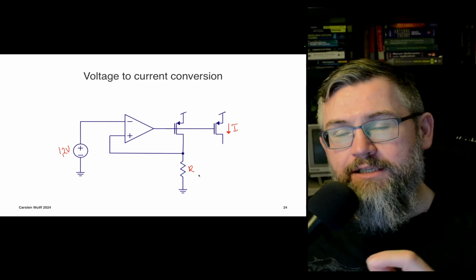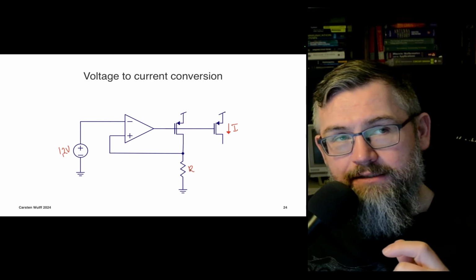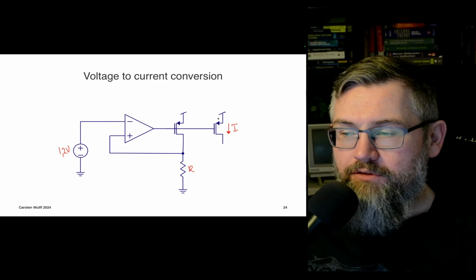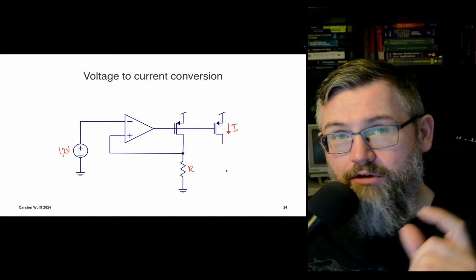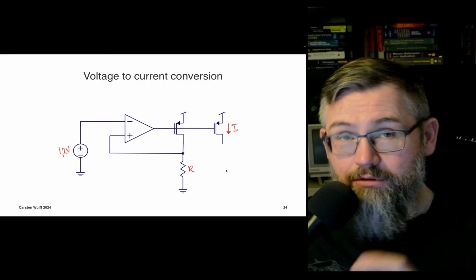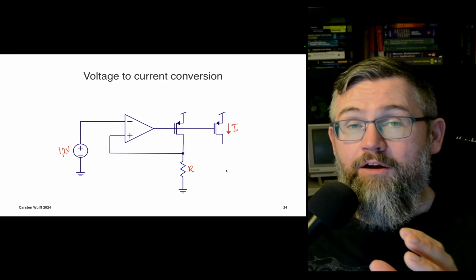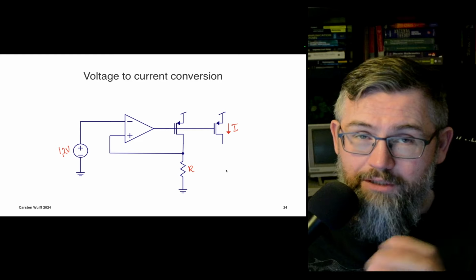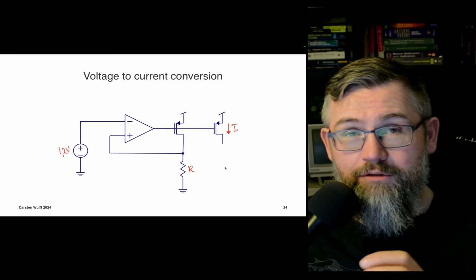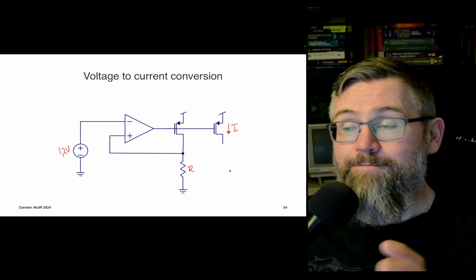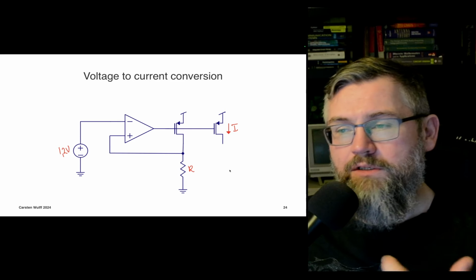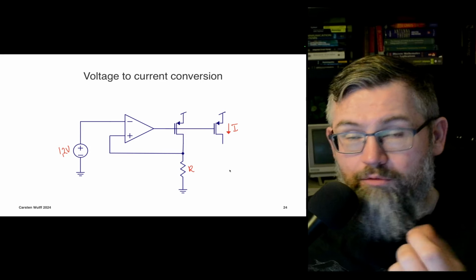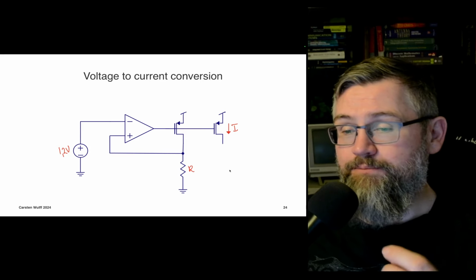And what you should realize now is that if I have exactly the same resistor on the other side of the chip, I can just take a current, put it into that resistor, and the voltage across that resistor, as long as it's the same, will be 1.2 volts. I can freely choose what the voltage is going to be, depending on the size of the resistor that you use at the other end, but you see the point. This is a good way to distribute currents, bias currents, across the chip, or indeed reference currents for that matter.